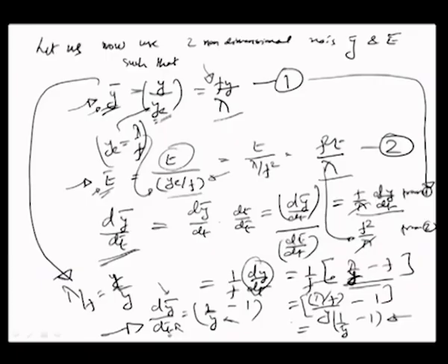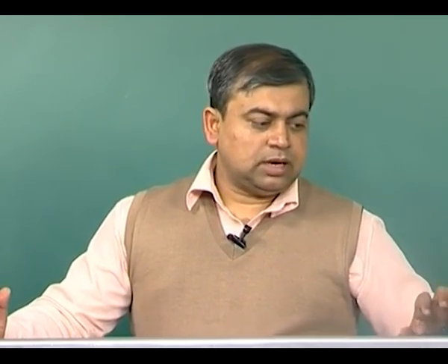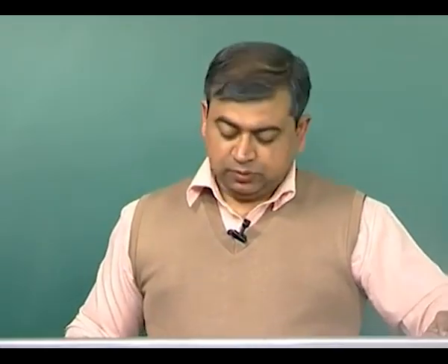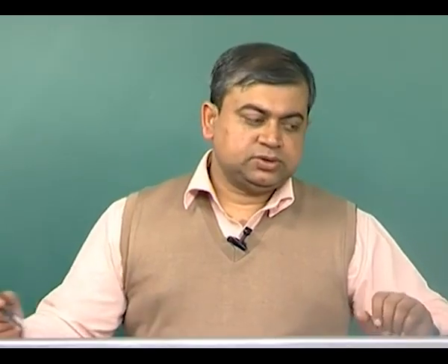And now what you can very easily observe is that this equation has become independent of the feed, because the feed is buried inside the information for the time ratio t dash, which is equal to the equilibrium gap per unit feed, ye by f. So that is how you have a relationship between all ratios, a non-dimensional relationship. What I am now interested in is to manipulate this by integrating with respect to time to see how y dash and t dash would vary. So, let us look at that part.